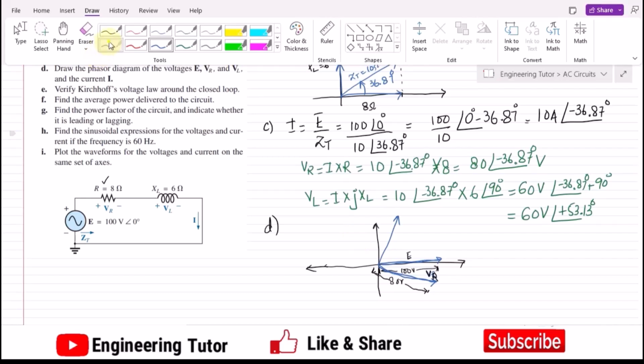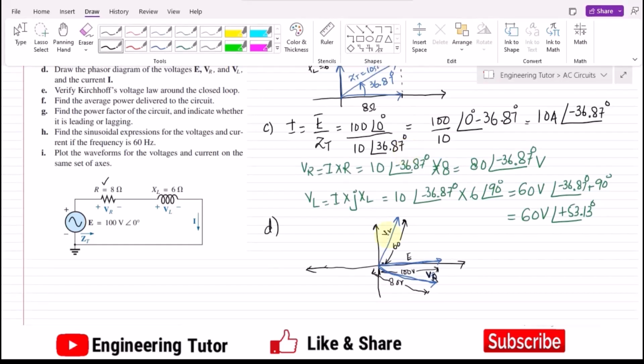The magnitude it has is 60 volts, and this is V of L. We have written it, and the angle it makes is positive 53.13, and the angle V of R is making is minus 36.87. So that's why V of L and V of R are 90 degrees apart from each other.